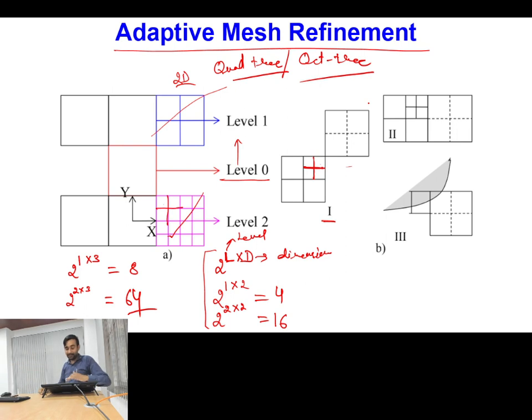So it means when I will be doing this type of arrangement, then there will be a smooth transition of grid from the finer zone to the coarser zone. Okay, if you have a smooth transition, then you will be able to decrease the error which is happening while you are transferring fluxes across the boundary.